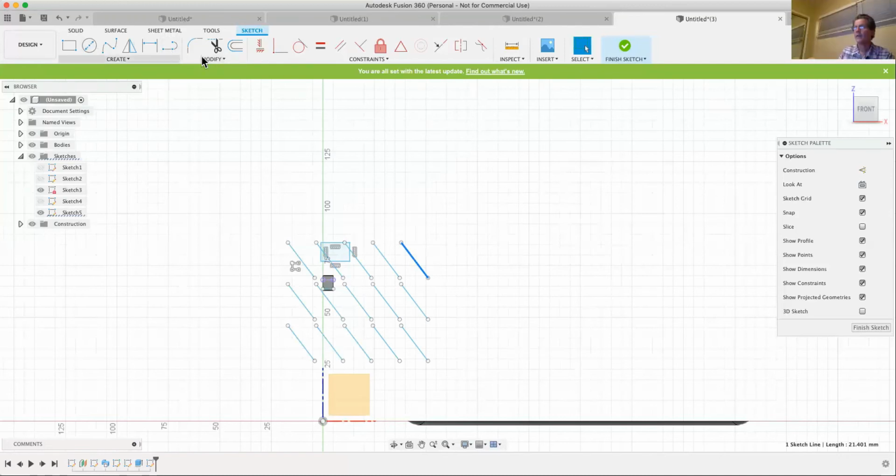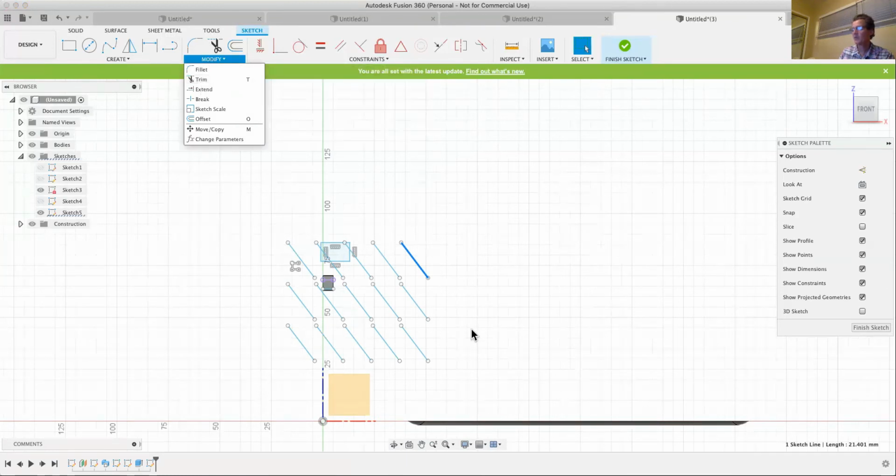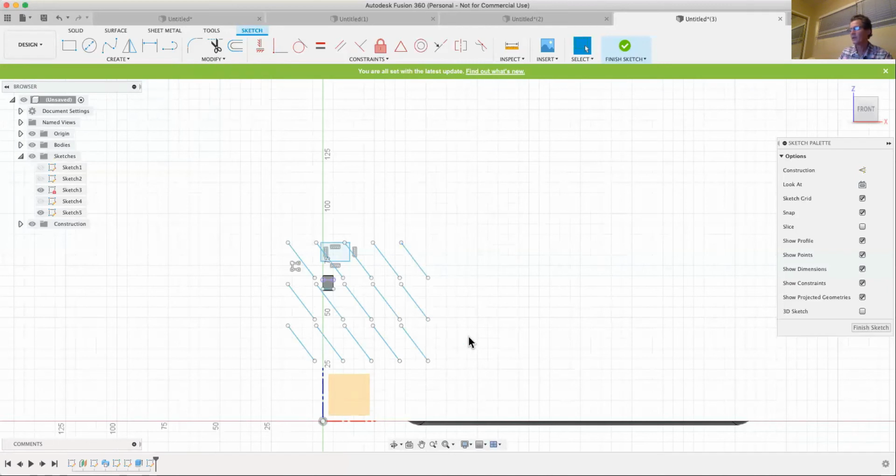Right. When you're in Sketches, there's a bunch of modification tools as well. You know, fillets, we know, trims, basically to the nearest boundary. So if something crosses something else, if I hit L for line and L for line and go across a bunch of existing lines, now if I hit trim, it'll take whatever's between, or the end to the boundary.